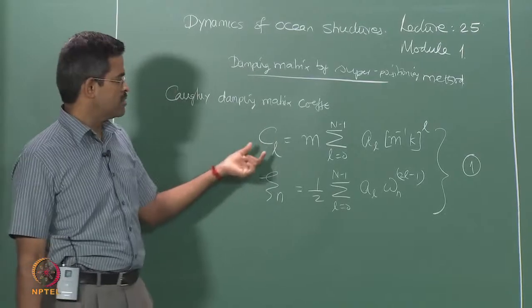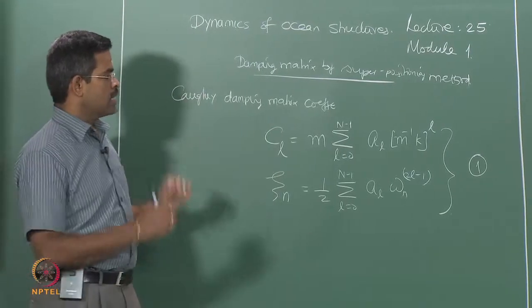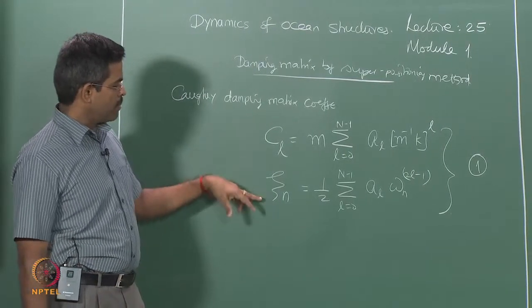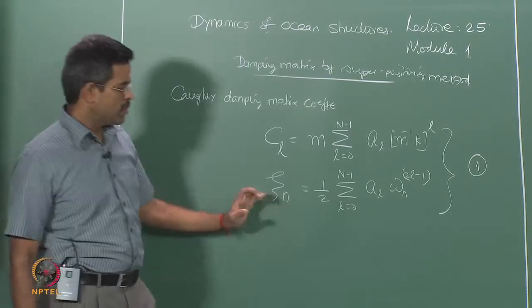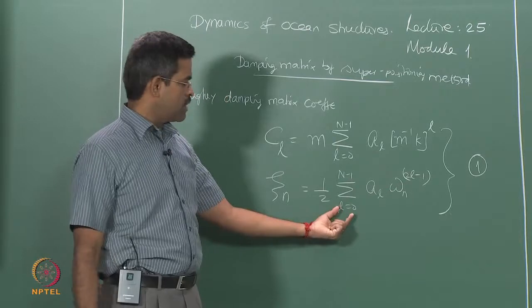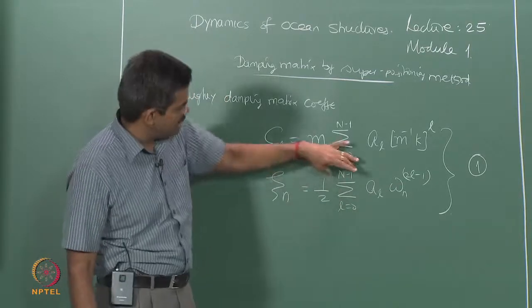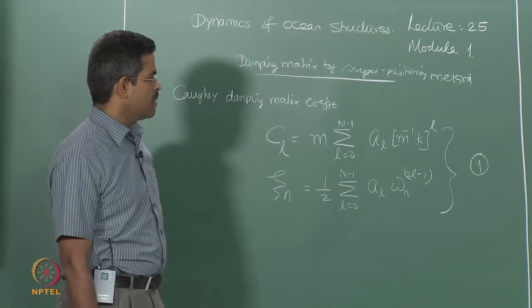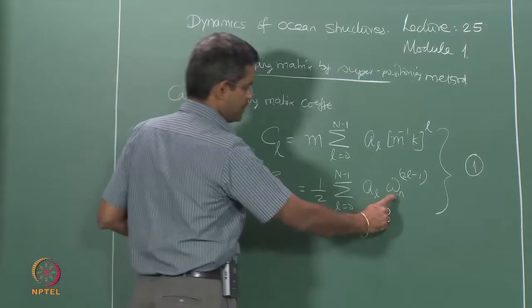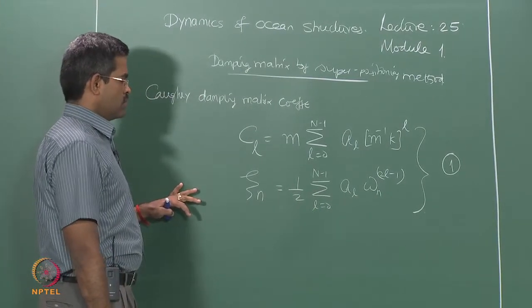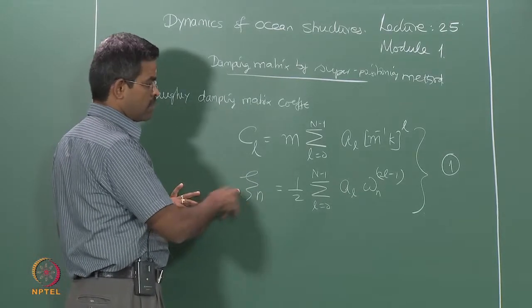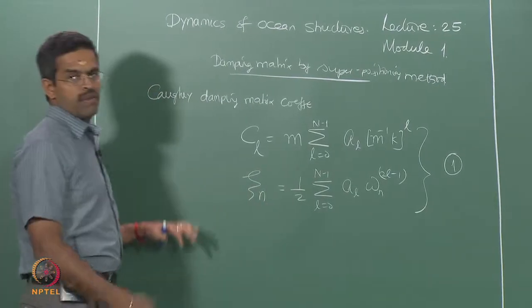You can always find the coefficients C1, C2, C3 so far, assemble them, and the corresponding damping ratio in the nth mode will be given by this equation. Again it is varying from L to n minus 1 or J, whatever we discussed yesterday. So, if you know the frequencies, you can easily find out the values of zeta in every frequency or every mode.